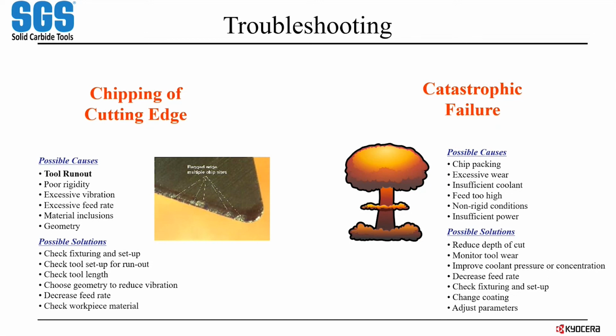The tool's going to start pushing. It's going to spike the pressure, and that tool is going to pop, or your piece is going to move, and then you got a lot of problems going on at one time. But chip packing, excessive wear, if that tool's again worn out, it's pushing, it's not cutting, it's going to blow up. Not getting enough coolant into the cut, same thing. It just gets hot, wears down quickly. Now you're pushing and not cutting.